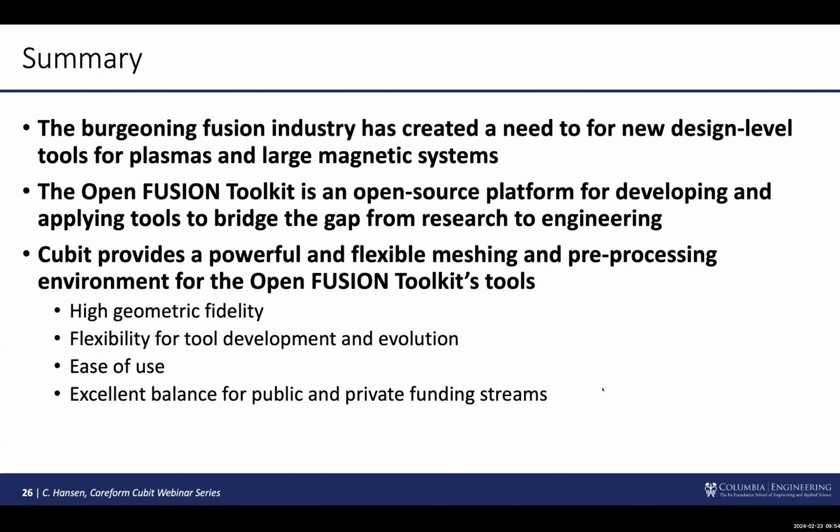We do have functionality in the code to do static refinement of the grid to build a multi-grid mesh, which we use for some of our solvers. In that case, as we're refining the surface of the mesh, we use information from the higher order elements, if that's present, to retain the curvature that existed in the initial elements.